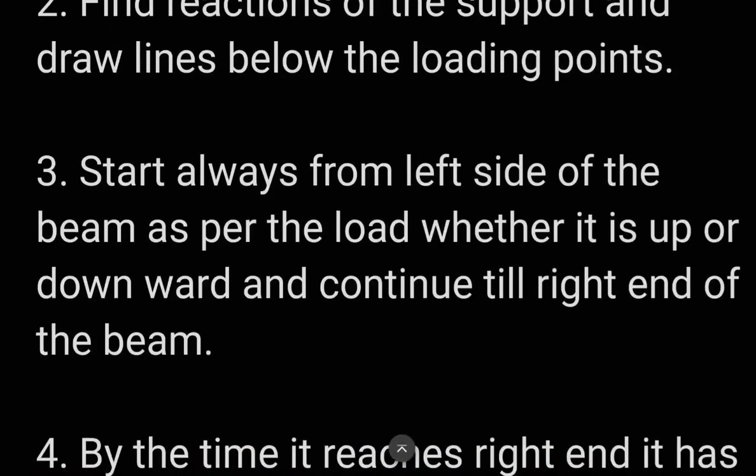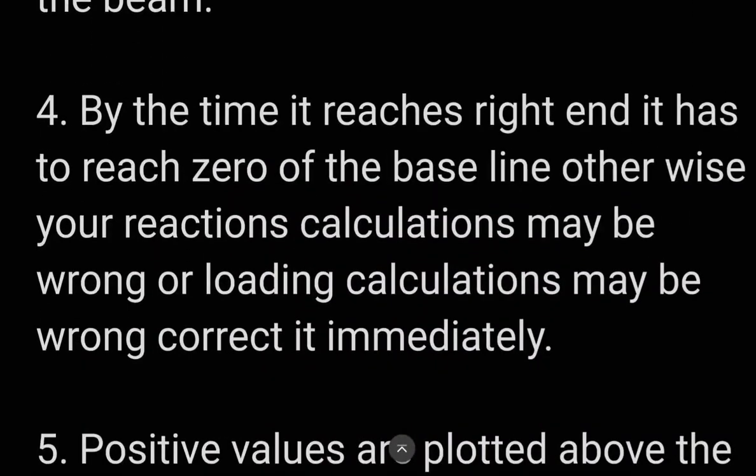Number 3. Always start from the left side of the beam, following each load, whether it is upward or downward, and continue till the right end of the beam. Number 4. By the time it reaches the right end, it has to reach 0 on the baseline, otherwise your reaction calculation or loading calculation may be wrong. Correct it immediately.